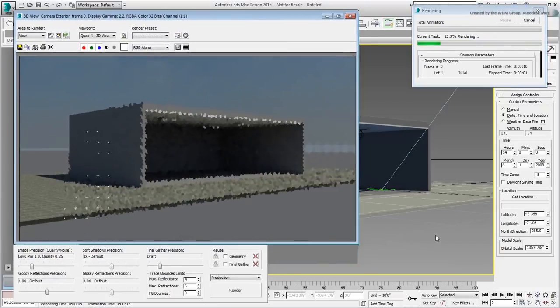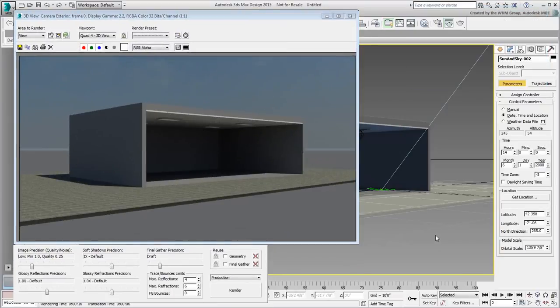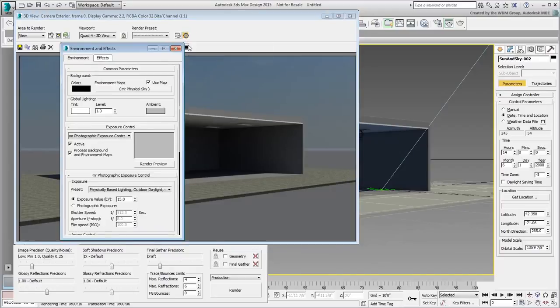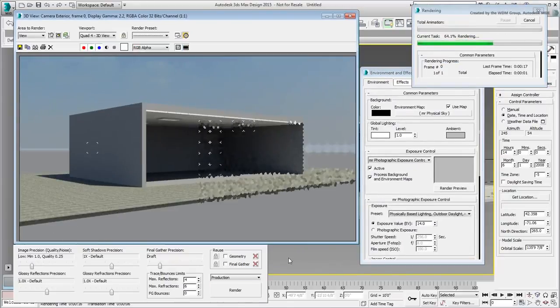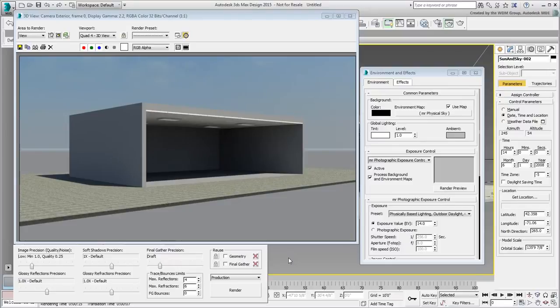In general, the rendering is still a bit dark. You'll need to adjust the exposure value in a second. Click the environment icon to access that dialog. Set the EV value to 14 and try again. This is better. Overall, the scene is brighter, and we can make out the inside of the room. The clouds in the background are a little less visible, though.